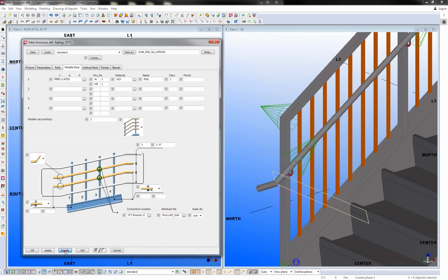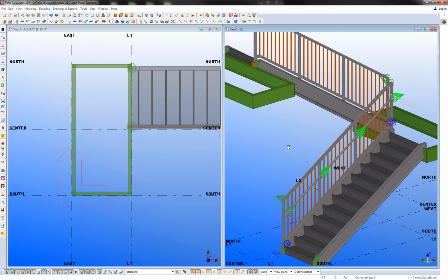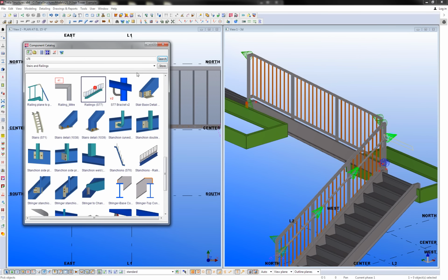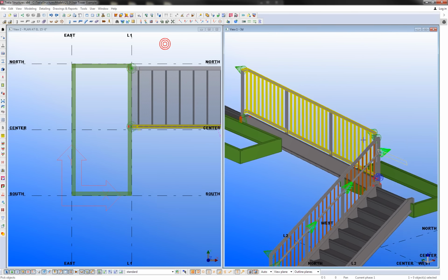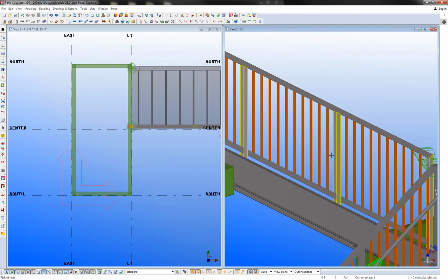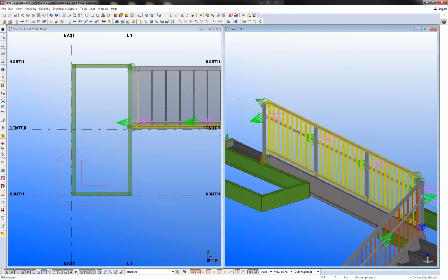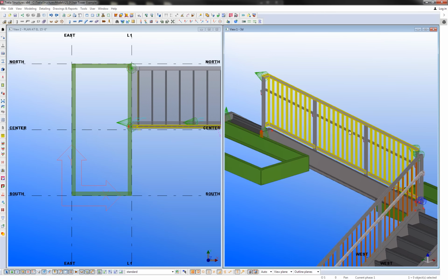I do want to show you though how you can make some of these bends and finishing parts custom using some manual tools like Polybeam. So I'm going to leave that as is for now. So I will go ahead and use these same settings on the upper rail. So I'm going to single click to activate the command, and then just pick those upper posts in order, and finish with a middle mouse click to create the rail at the top.